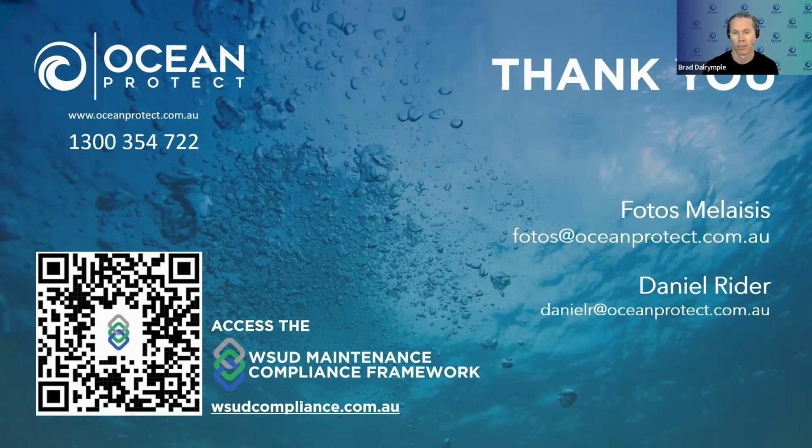A question for Photos. I think the technical definition from Work Safe Australia would be that any pit greater than 2 meters in depth is classified as a confined space. Now, if a pit insert is installed inside a stormwater pit that's greater than 2 meters depth, then I would technically say that is referred to as a confined space, and then the appropriate plant or equipment should be set up in order to service that appropriately.